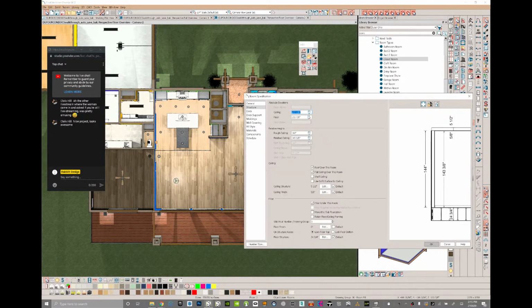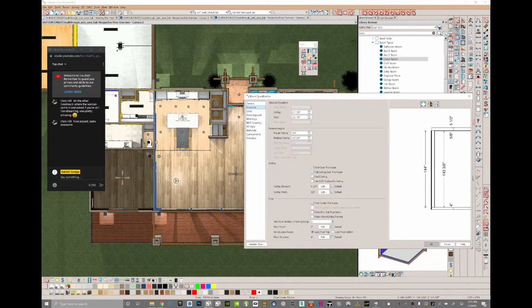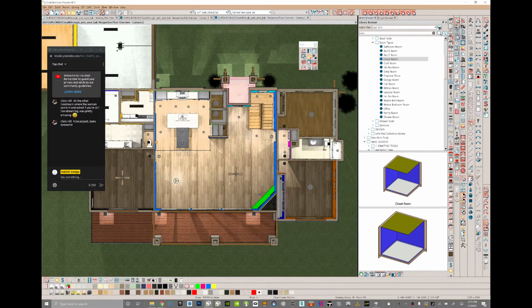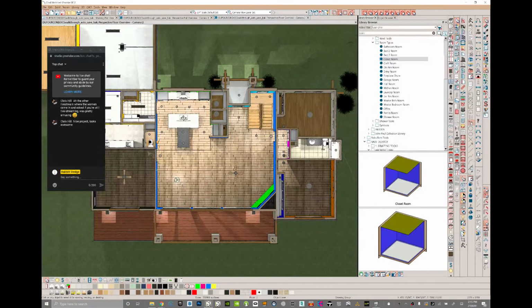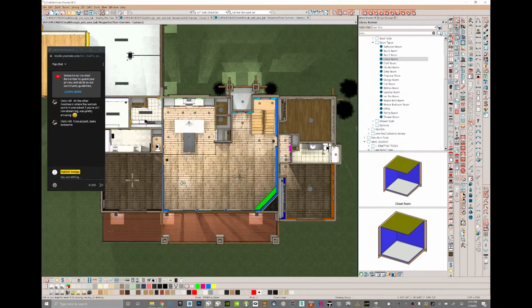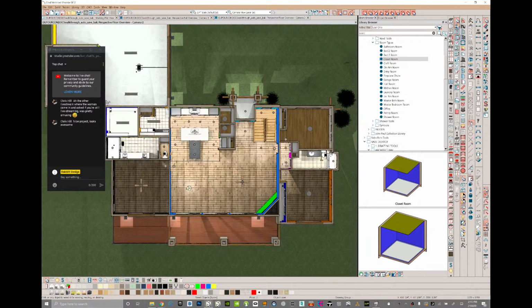I don't know what's going on with this floor. Don't have a default floor there. Maybe covered porch. Let's change this to actually a porch and get the settings that come along with that. It's going to retain a ceiling and a roof. That's fine. There we go. But this is just for the purpose of showing this rendering technique. Oh, see, we did get some lines. You can see here that the pattern is at a 90 degrees, so that's something that you'd have to fix.